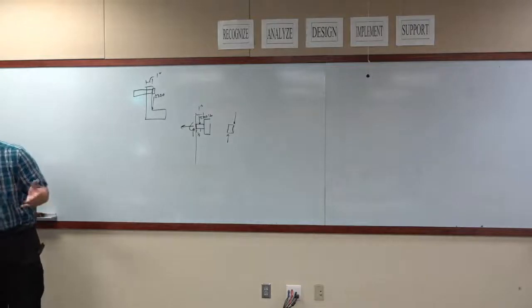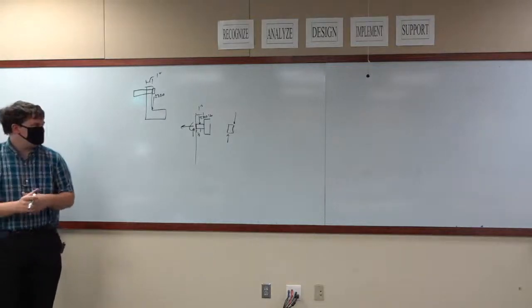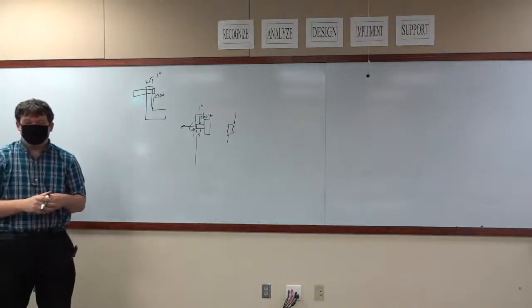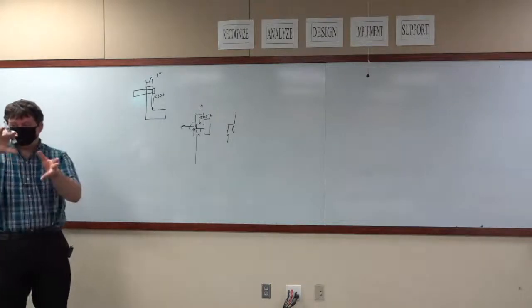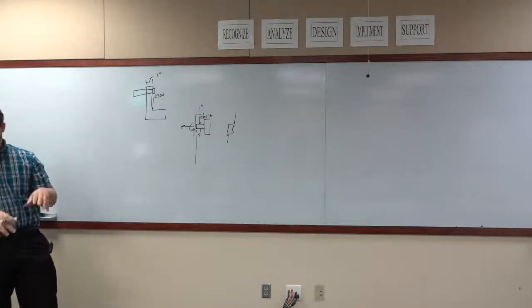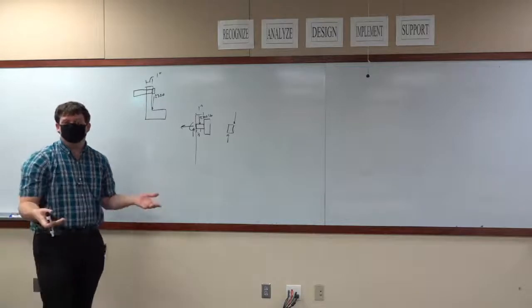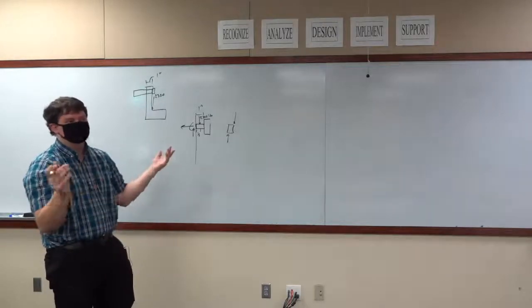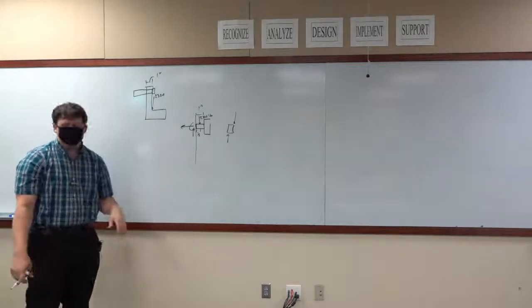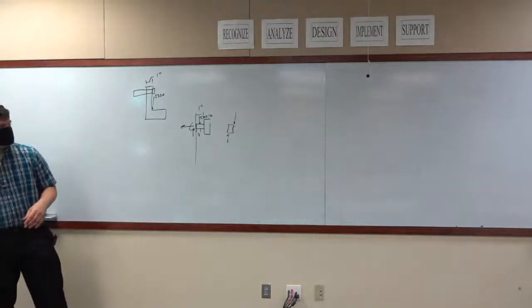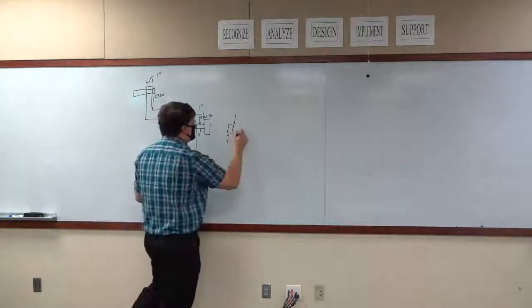Which we know isn't true. There is a moment involved. But some of that moment is actually going to be carried by the bracket, because that bolt can't turn inside of the hole, if you make the hole tight enough. If you make the hole too loose, then yeah, okay, there's a moment. But basically, you're carrying 2,300 pounds of shear load.